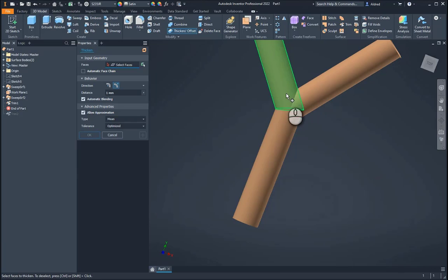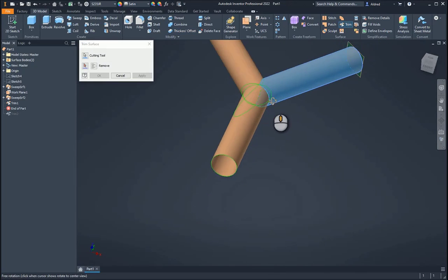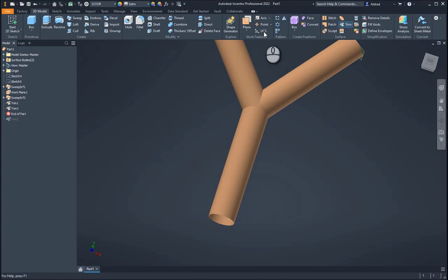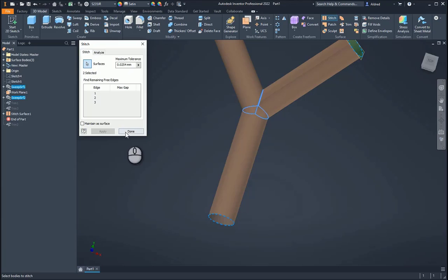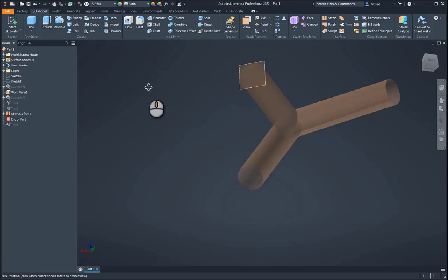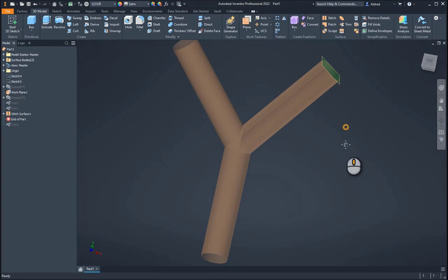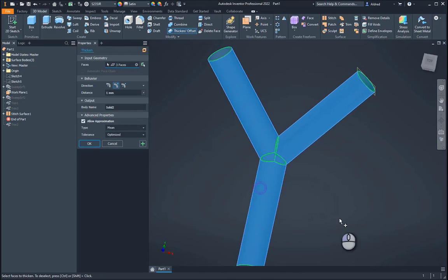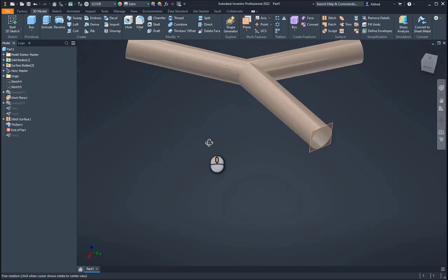So you can see there it's actually coming out over there. So I found where the problem is. Let's go and trim that, and I want to get rid of that piece over there and apply. Okay, so there and there. Let's try and apply this now. There we go. Fantastic. Now I've got my surface over there, and to create the wire piece with an actual thickness, just go to our thicken tool, select, select, and select, and okay, and it creates our wire piece over there.